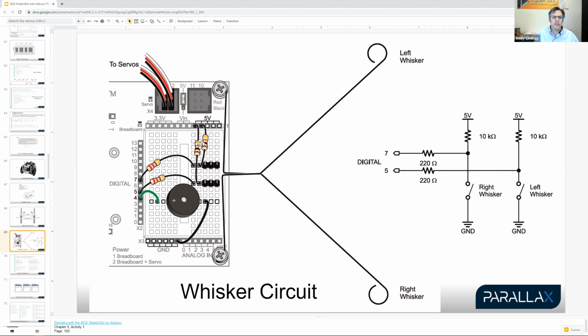So try to make sure you can differentiate between brown, black, gold and brown, black, red. Brown, black, red is 1,000 ohms or 1 kilo ohm, and brown, black, orange is 10,000 ohms or 10 kilo ohms. And like I said, if you made that mistake here and use brown, black, reds, sure, it'll still work. But coming up in another activity, if you accidentally use brown, black, orange when it's calling out for brown, black, red, you and or your students will have a robot that might seem like it's blind in one or both eyes.